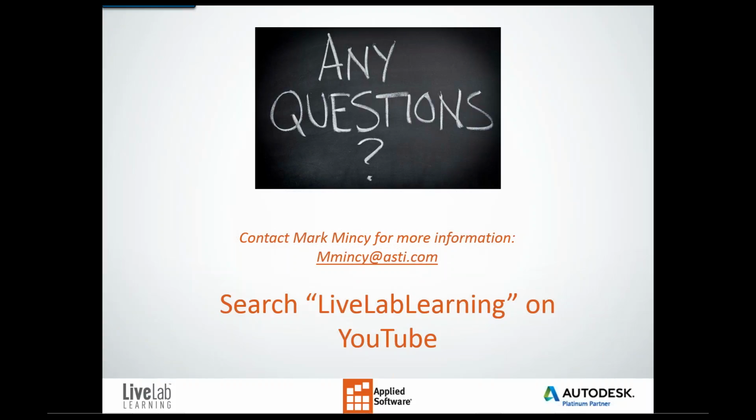So let's say, Kit, we're working in Revit 2016, latest, greatest version, right? Mark, I'm going to pick on you, for example. Mark's our engineer. He is working in Revit 2014. When he sends us a drawing in 2014, we open up that drawing and save it. It'll be in Revit 2016. When we send it back to Mark as the engineer, sorry, Mark, it'll only be in Revit 2016. In the previous versions, they won't be able to open it.